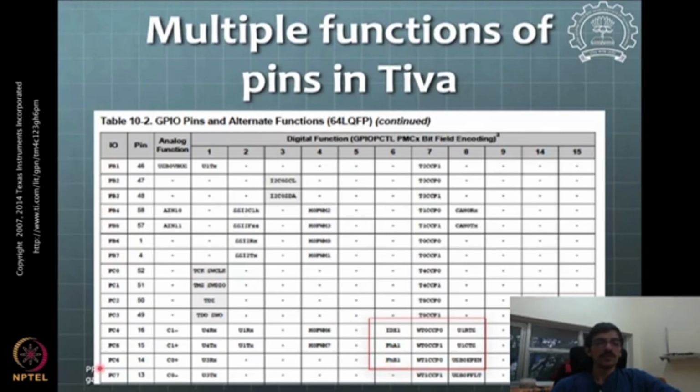Okay, so in this case, they fall as PC. So these are the names of general purpose input output. PC6, PC5, and PC4. Okay, these pins you'll connect to your encoders, and then you hope that you configure this appropriately. So naturally then there'll be somewhere you need to say that I'm using these pins not as general purpose input output, but I'm using these pins as encoder outputs. Okay, so that reconfiguration of the pins needs to be done somewhere. There will be some commands to do that.